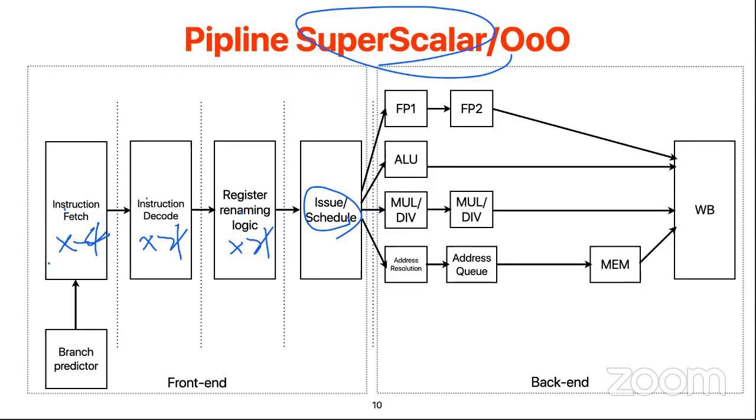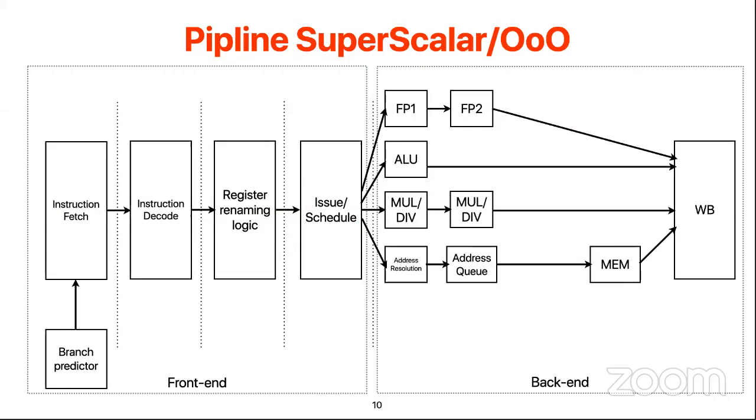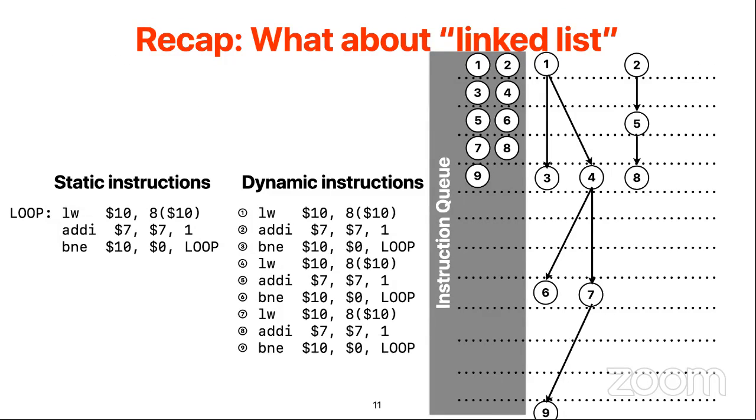And with the superscalar pipeline, as I mentioned, you can imagine the modern processor is actually having a decoupled front end and a back end. The front end means the interface between your memory and your processor in terms of fetching, decoding, and renaming instructions. And the backend is the actual pipeline where you are executing instructions. So those are decoupled.